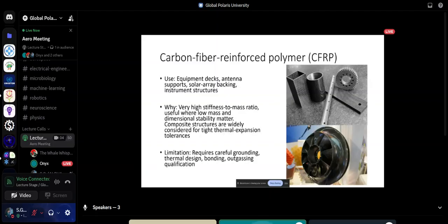And then also outgassing qualification. Just as a way to jog our memory from the last meeting, outgassing is whenever vapors in a vacuum environment separate from a solid. This is usually common in composites, and this fits the use case. So outgassing qualification means essentially removing all the vapors from this before it gets assembled into the structure, and then continuous monitoring until launch.